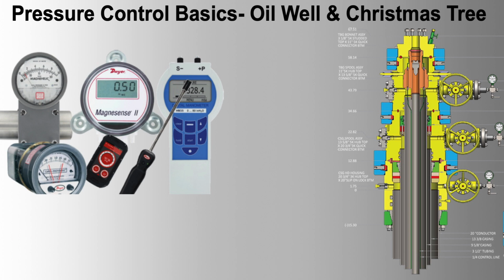Maintenance. 1. Scheduled maintenance. Calibration: regularly calibrate downhole pressure instruments to maintain accuracy. Inspection: conduct periodic inspections of downhole equipment to detect and address wear and tear.